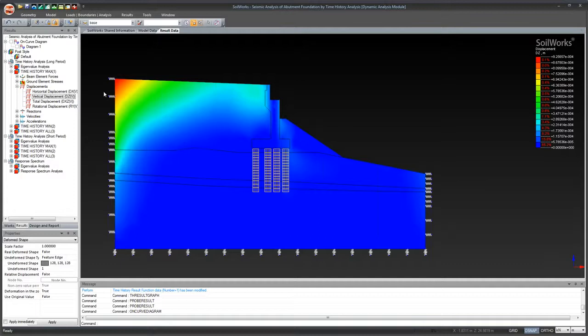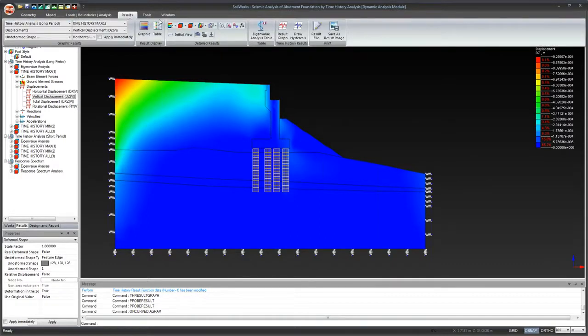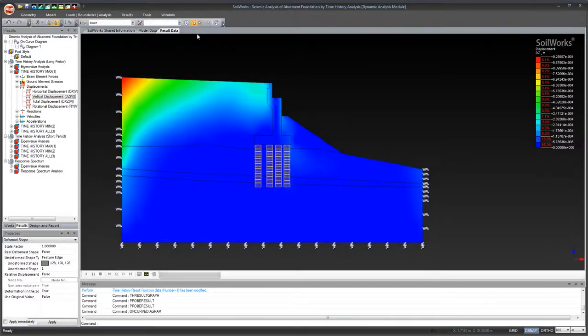So first let's go to record animation. Go to results, and then our detailed results here. These are very specific to the dynamic module. Click on this icon here. This is the record animation feature. Just click on it, and when you do so, it goes away at the top of the screen. But here, as you can see, there's a function called record. So just click on this icon. Okay, and then it'll record the displacement change over 20 seconds.